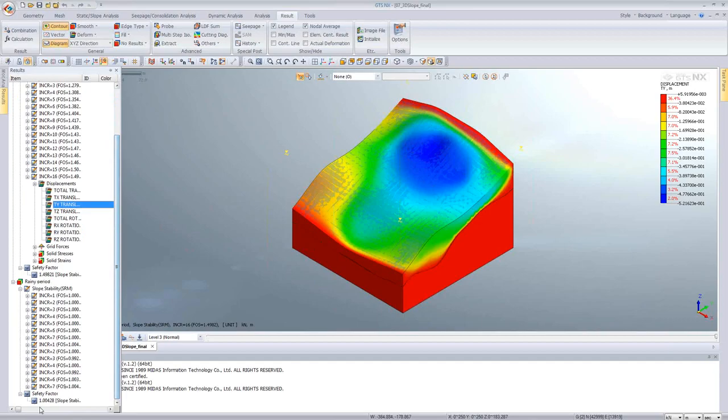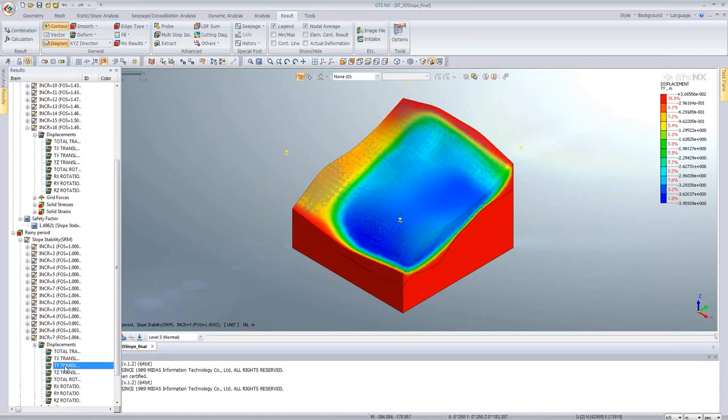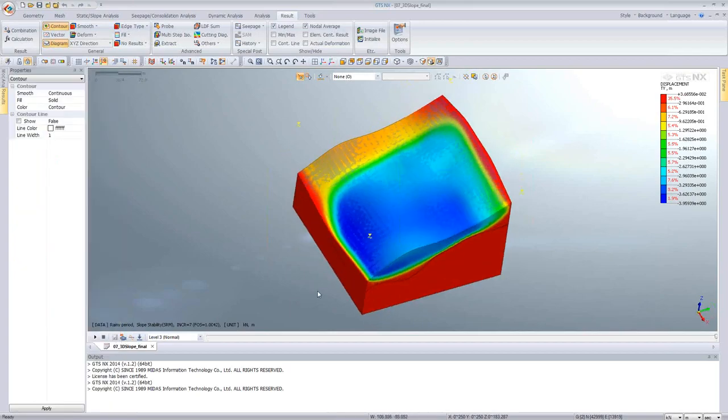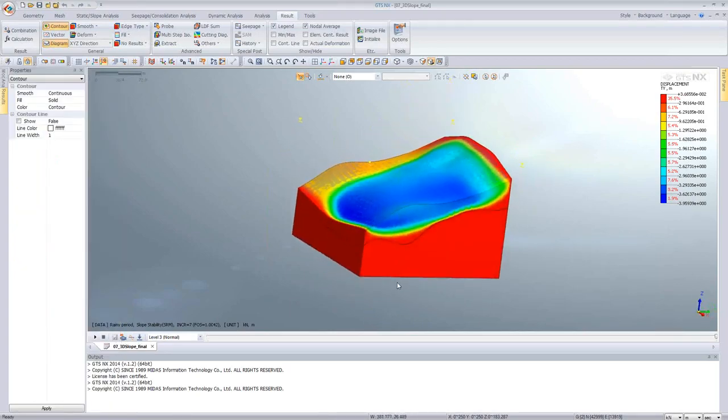Similarly, for the rainy season, if you consider Ty, you can see how it is going to fail. So this is how basically we determine the failure surface in case of the SRM method, and in accordance you can provide the reinforcement, more reinforcement or high dense reinforcement for that particular region. So this is how you can consider even 3D models for your slope stability checks.